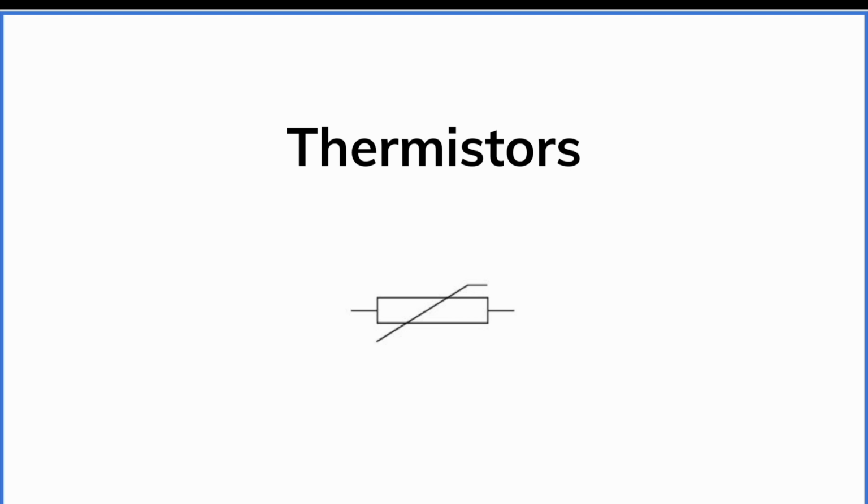Another very useful type of resistor is called a thermistor. You might think thermal physics, it's related to the temperature. As the temperature increases on a thermistor, the resistance decreases. There are lots of applications for this. They can be used to control the air conditioning in a room, turning off the AC when the room reaches a temperature, or in ovens and stoves. It can sense when the temperature reaches a certain value, and it stops providing current. So a lot of really good uses for thermistors as well.